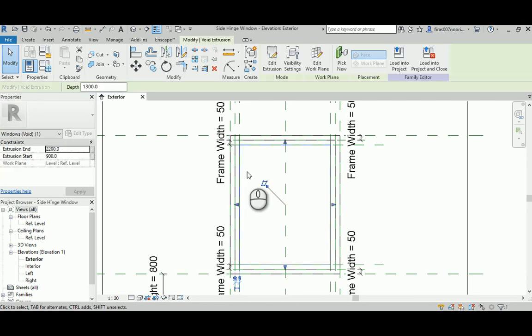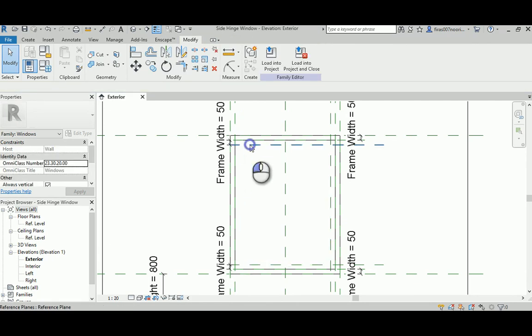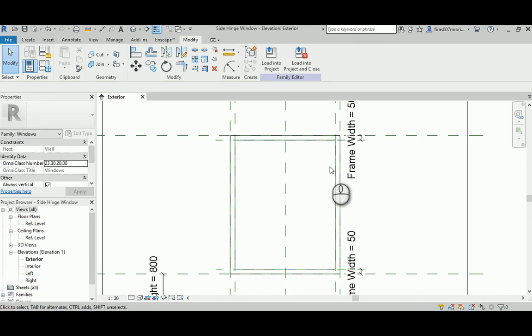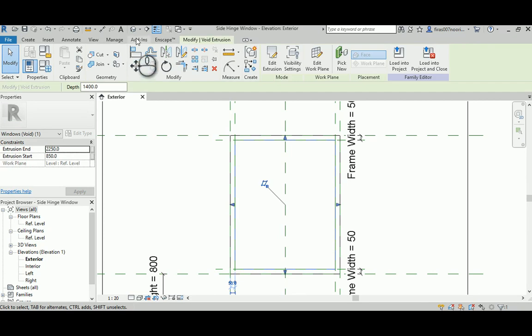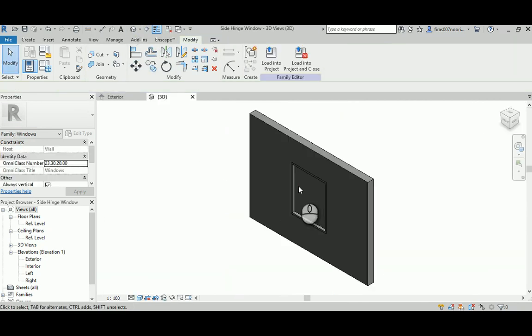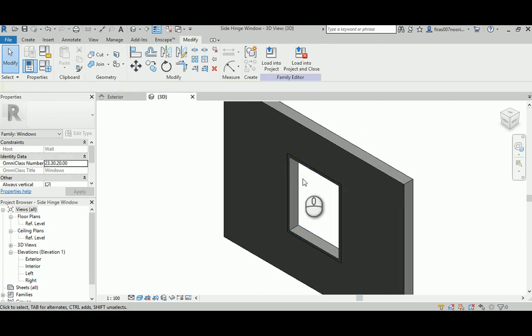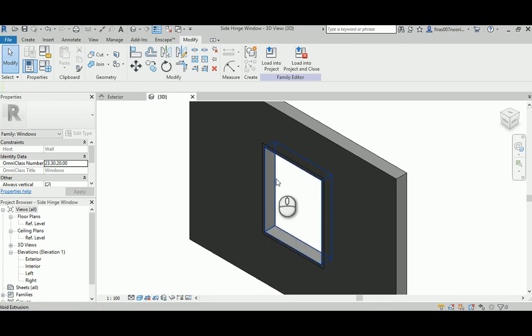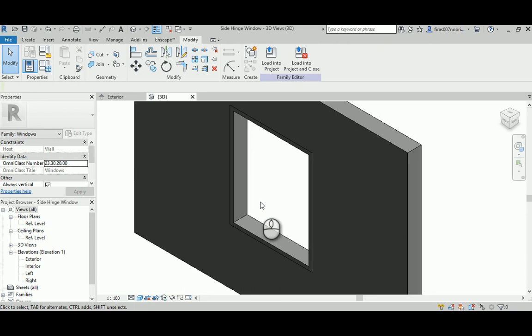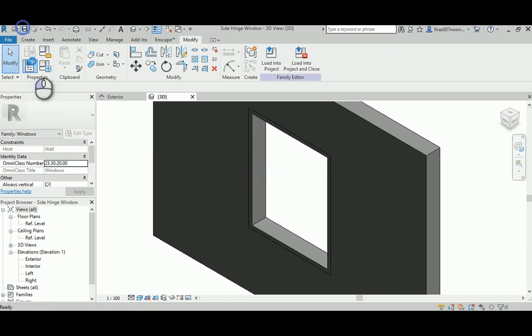So it would be a good idea because the current setting that I have doesn't allow me to share the operable part. The frame is designed to be fit and based on the extrusions and subtraction as a solid and void, to create the void in here, to create the frame here, and then the second frame for the operable part and then the glazing. So what I'm going to do, I'm going to leave this, save it.